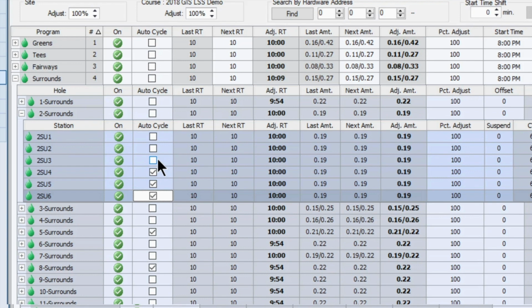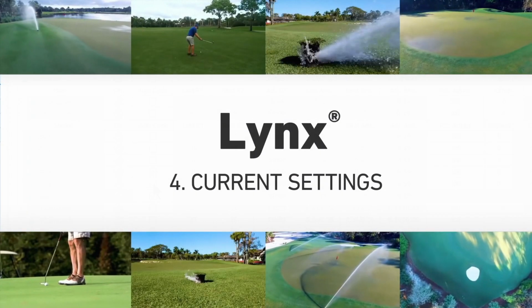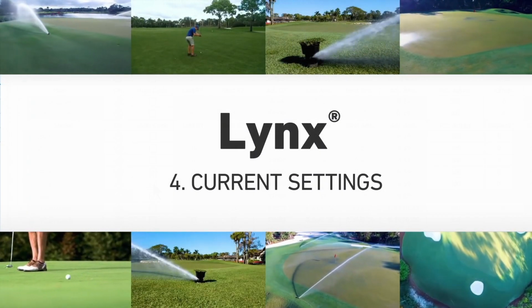Auto cycle is a tool that can be misused. It can cause the system to be less efficient, take longer, and put more stress on the piping. So the key is to use it where it is needed. Instead of turning it on for the entire golf course or an entire program, drill in and choose the holes that you need it on or the individual stations that you need it on. In a fairway, you may not need auto cycle on the entire fairway, but you have some mound areas where the water can start to run off the mound and down to a low area. So you want to choose those stations to auto cycle.